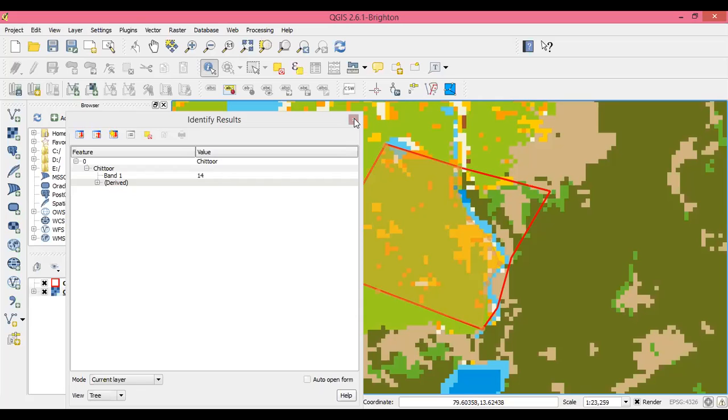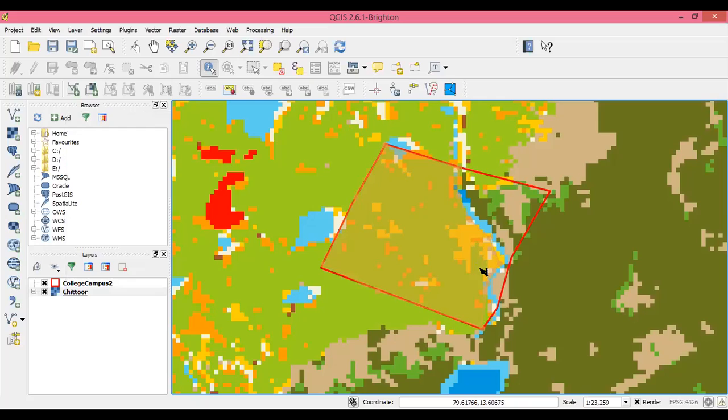All right. So now this is the part where it gets interesting. Now in this particular case where I randomly drew this polygon, it happens to be agricultural area. Let us assume that it is all going to get converted into a college campus. Obviously the farmers are not going to continue coming and cultivating inside the campus, so that cultivation will stop happening there. But instead of having that cultivation, maybe some of it will get converted into built up area. Built up area means you'll have buildings and roads and other infrastructure and so on. So therefore that area is going to become impervious.